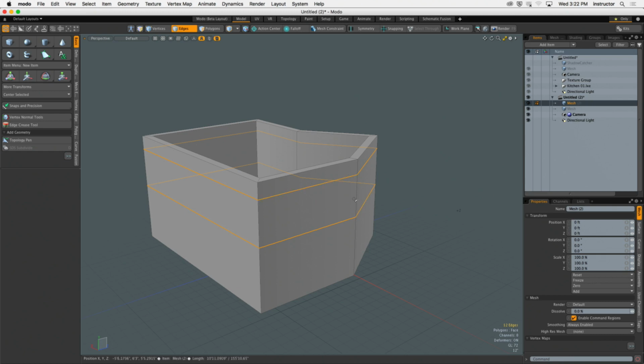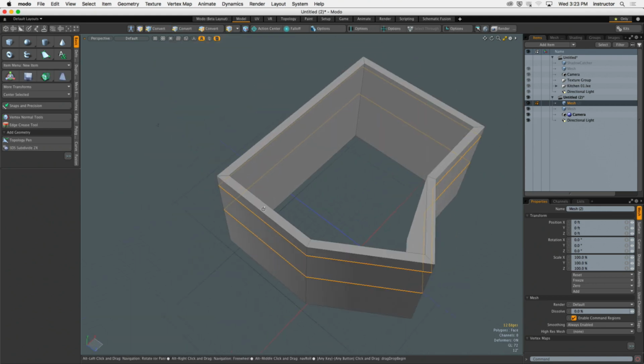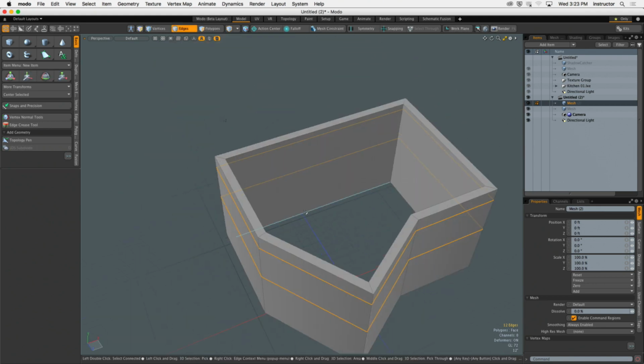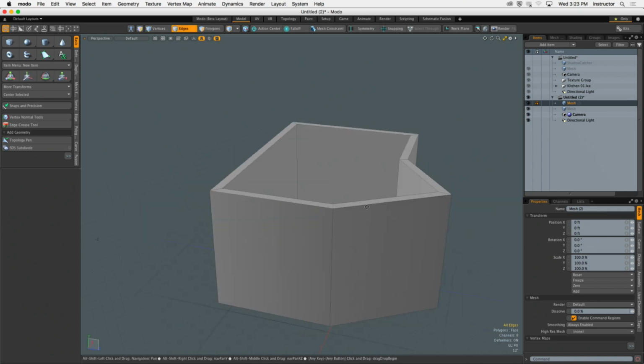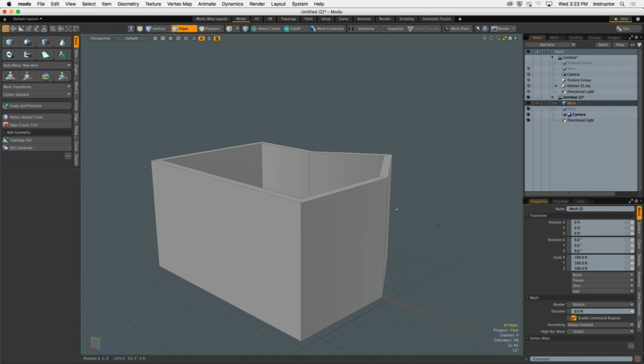So let's delete this, and we'd have to do the inside as well. I have to slice the inside, and it would have to be perfectly aligned to the location of the slices on the outside of the house. Problems, problems, problems using our existing slice tool set. So let's get rid of those real fast and start talking about Booleans.